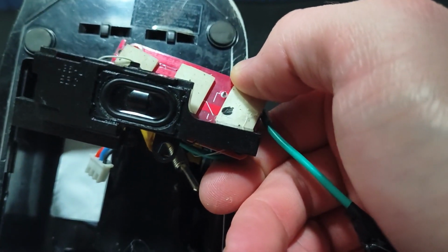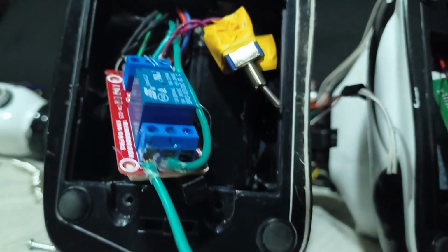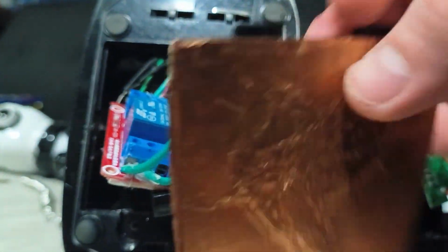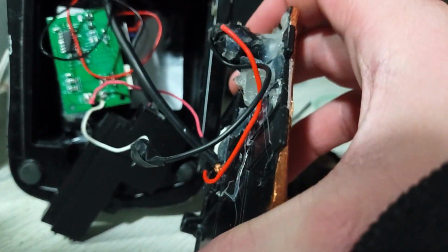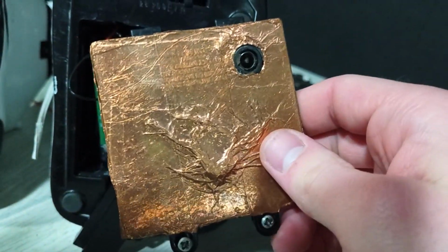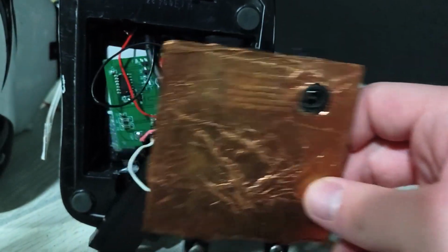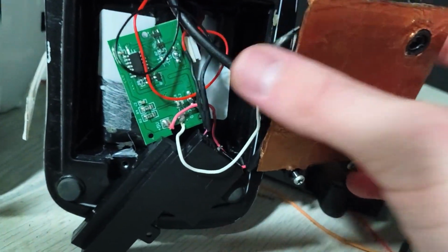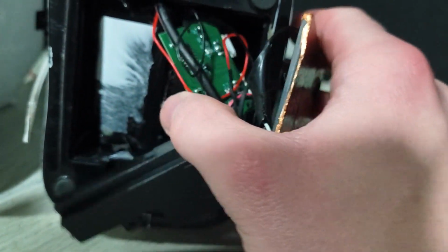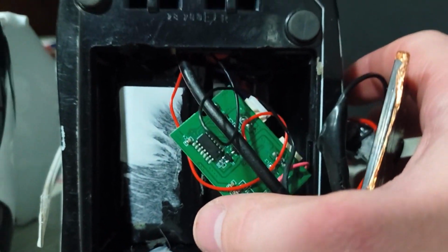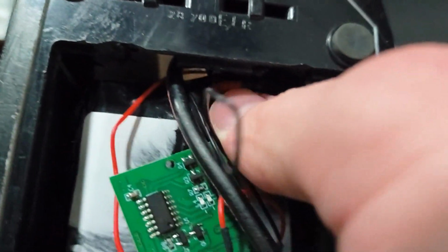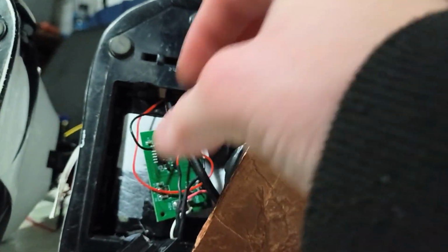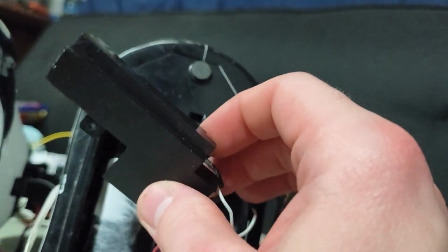There's that speaker, and that relay actually routes to a copper plate, and that's a positive battery terminal, and it's not always on for obvious reasons, but it connects directly to the battery system. In the other foot you have a 5 volt balance charging board that balance charges one of the batteries, and the other battery is always connected. Then you have a 5 volt barrel jack or USB Type-C connector to activate that 5 volt charging board, and you also need to Dremel out the front of each foot.